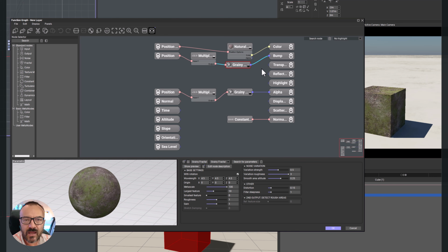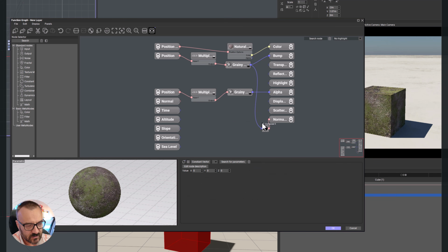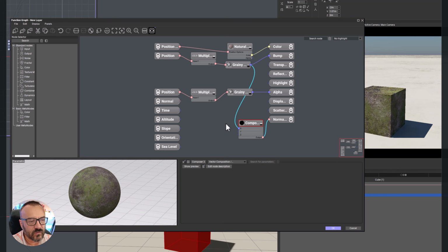Well, we can also do the same thing. We can say, like, from bump map, and this is the beautiful thing about the new view. If we connect here, you'll notice it adds a composer for us, and the composer takes inputs. In this case, all we have is one. Let's extend only the X composer. We don't have Y and Z, and convert this to our normals. We're kind of cheating because we have only one value. In general, it will expect X, Y, and Z, all of these parameters.